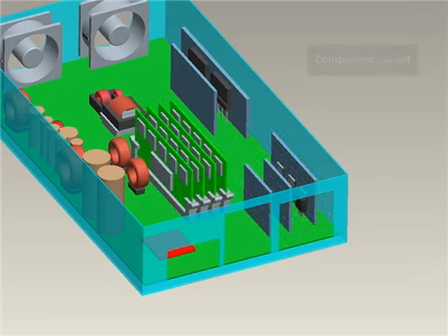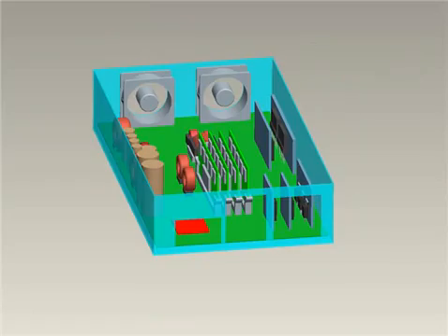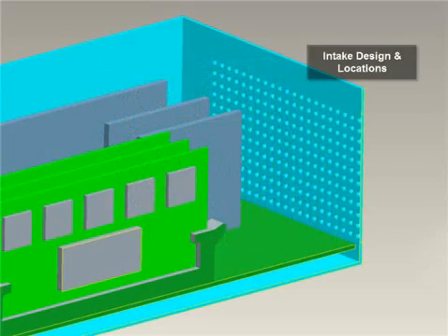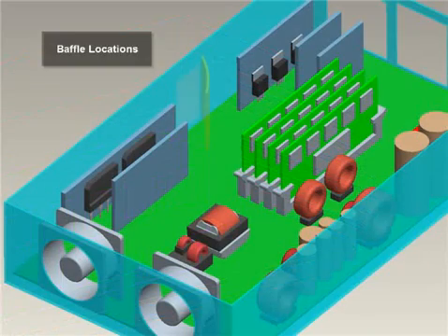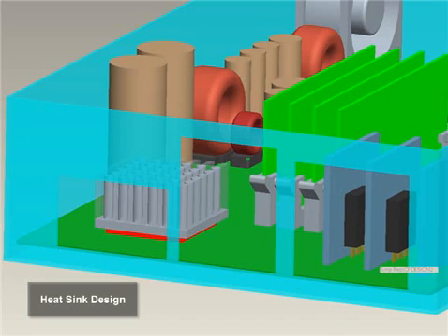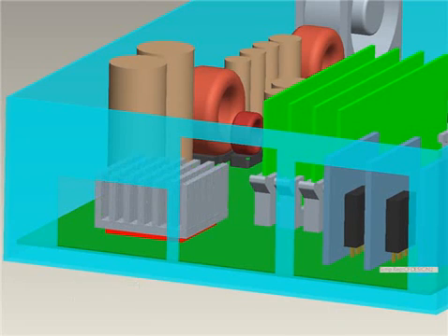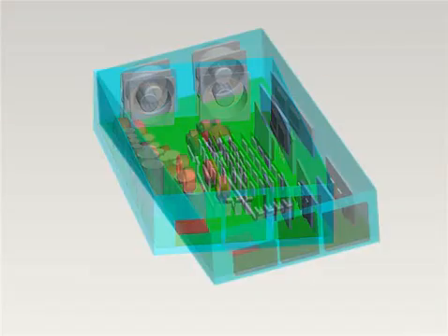Component layout, fan selection and placement, intake design and locations, ideal baffle locations, heatsink design, and optimization. All these items can be solved up front during the conceptual phase, giving you both quantitative and qualitative design insight before building a prototype.